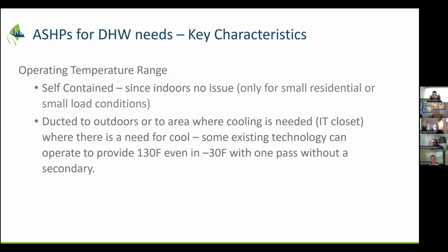So you do get to a point when it's really cold outside that, yes, we can still operate our units at -30, but the heat output may not be enough at that temperature. So yes, we have built-in electric backup heaters that will automatically top up and work in conjunction with the compressor to give you the heat you need.